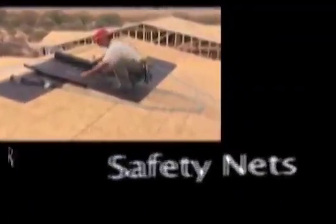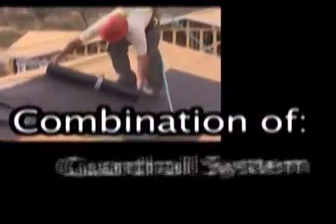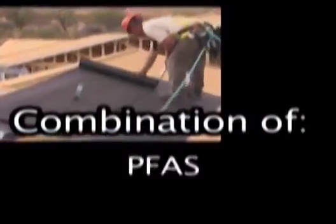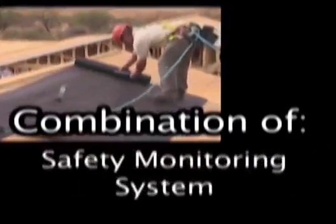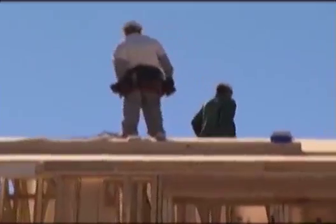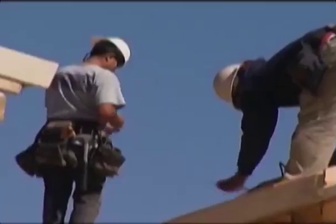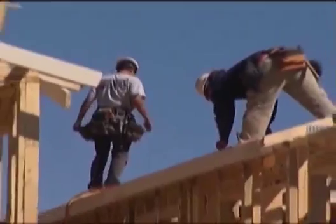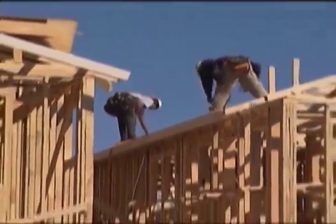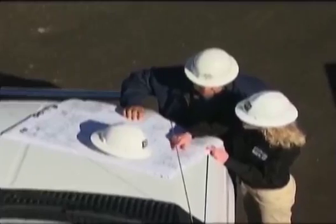Roofing work on low-slope roofs can use guardrail, safety nets, PFAS, or a combination of a warning line system, guardrail system, safety net system, PFAS, or safety monitoring system. Roofs less than 50 feet in width may use a safety monitoring system by itself. Residential construction requires the use of a guardrail, safety net, or PFAS. When it is infeasible to use these methods, or it creates a greater hazard to use these systems, an employer may develop and implement a fall protection plan.